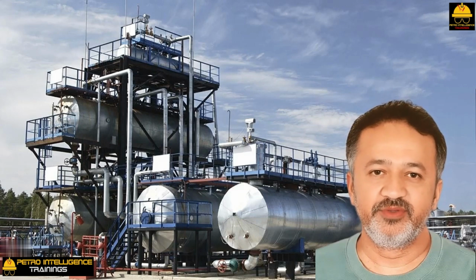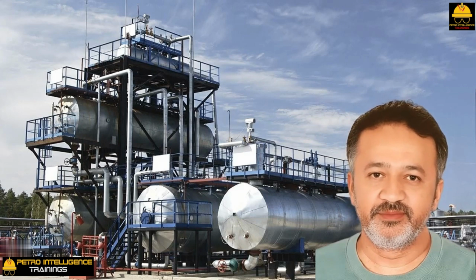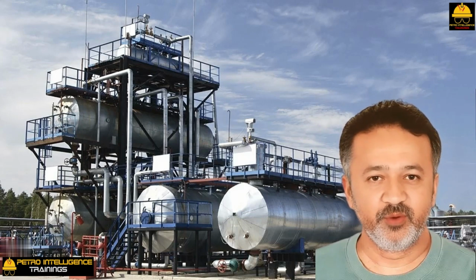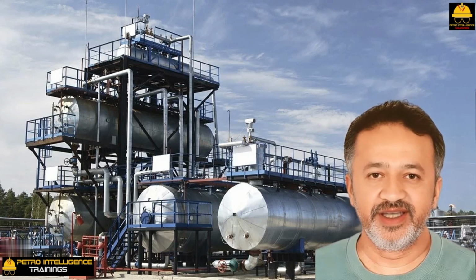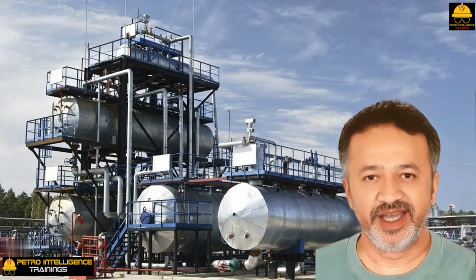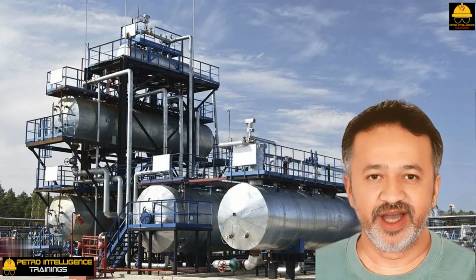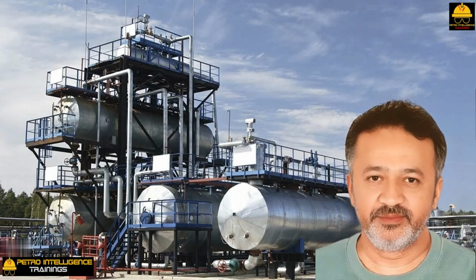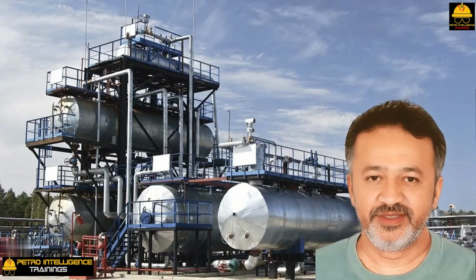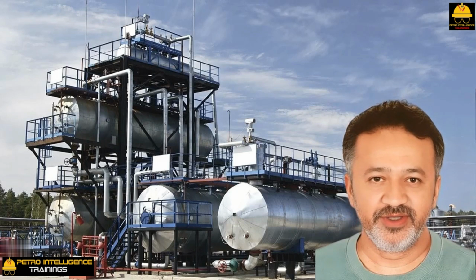Also, the hot lime softened water has variable amounts of carbonate contamination. When boiler feedwater is converted to steam, the carbonate deposits will break down into carbon dioxide and hardness deposits. The hardness deposits coat the inside of the boiler's tubes, interfere with heat transfer and overheat the tubes. The carbon dioxide, which is also generated from the dissolved solids, creates more serious corrosion problems in downstream heat exchangers.